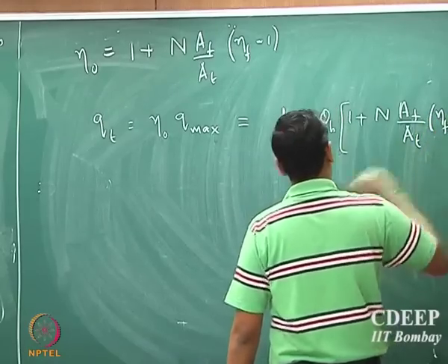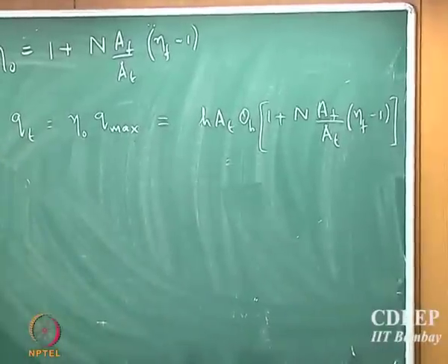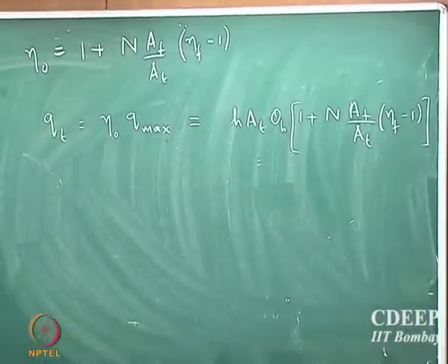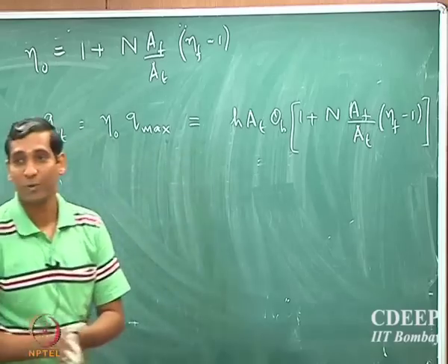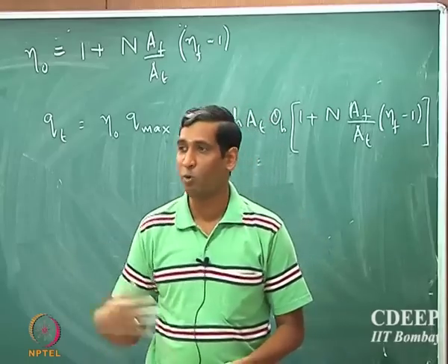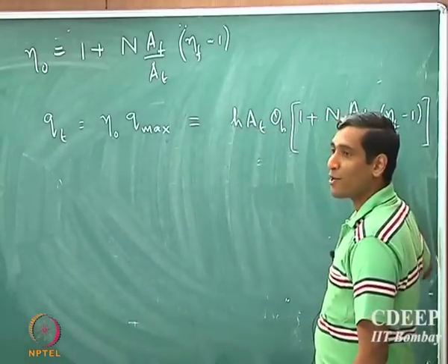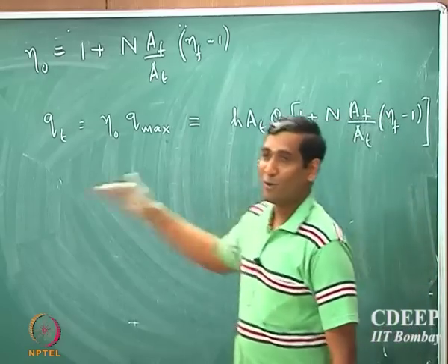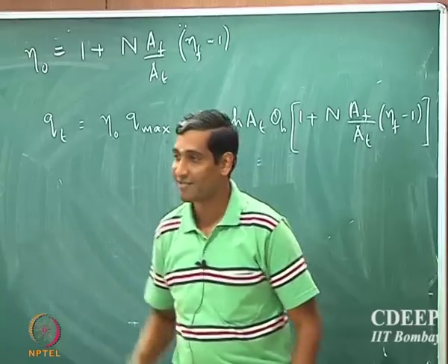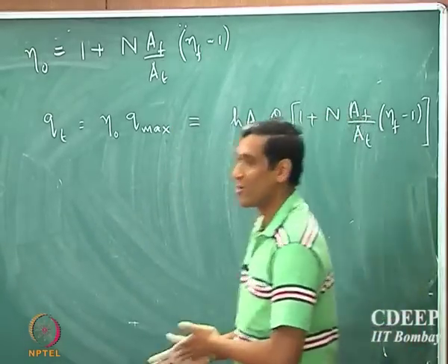So what happens when N increases? Does the heat transport rate increase? From this expression, that's what you would intuitively guess, because that's what you want to achieve. By putting many fins, you want to increase the heat transfer rate. Does the expression also show that? By increasing N, does it increase the total heat transfer rate? This is very important. Anytime you do such a quantification calculation, you should always check whether what you predict is exactly what you intuitively would guess. Yes or no? Why?